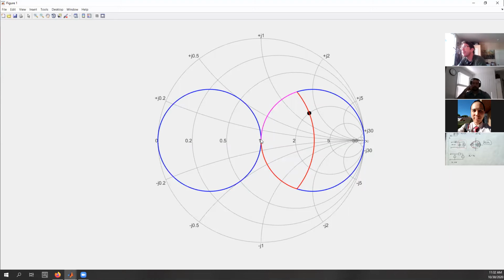When we were working in the low-high, are we still working in admittance, or have we switched over to impedance? You're technically doing both. The shunt is the one that will follow along this red arc here, these circles, and then the series will take me along these other circles. Can we give them a name? Just an admittance circle will be touching the left of the Smith chart, and then a reactance circle, or an impedance circle I guess, would be over here on the right side, touching the right end of the Smith chart. So you're kind of doing both, right?